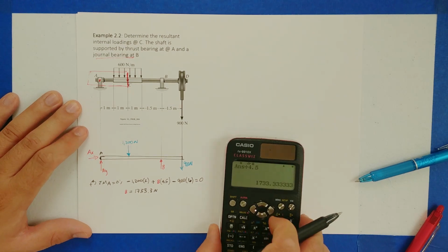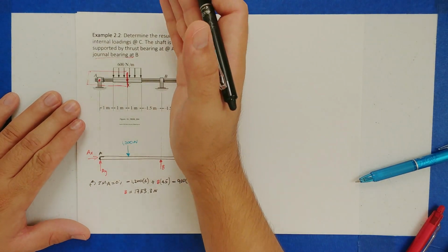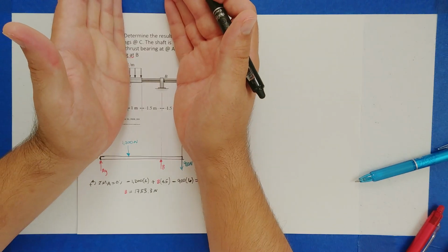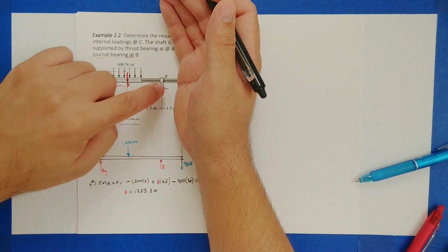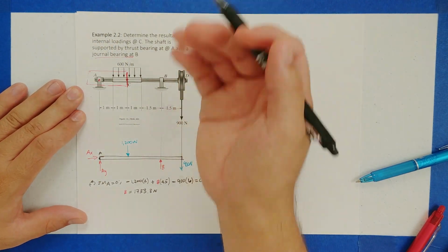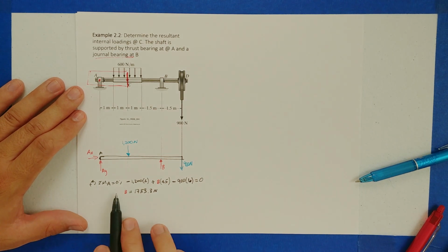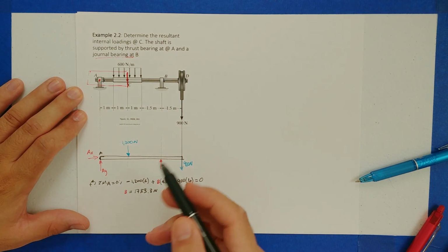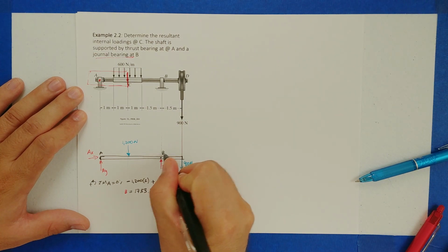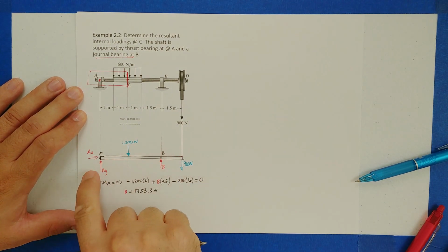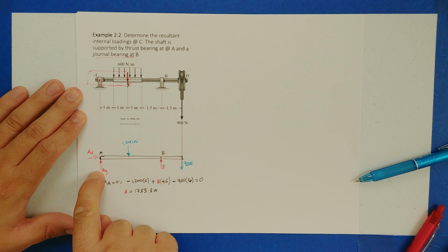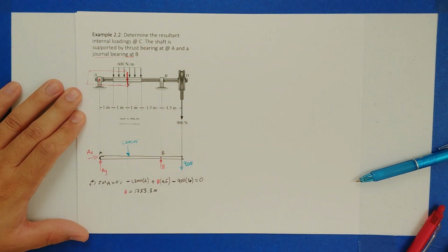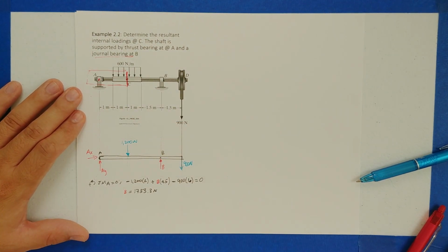With this, if you're trying to save time, you might be tempted to go ahead and use the right-hand section, since I already have my unknown, and move on. But I like to always finish the statics to make sure this number that I got is correct. How am I going to do that? Well, I'm going to do so by summing moments now at point B, figuring out what the Y component is, and then summing the forces in the Y direction to make sure all of that equals 0.